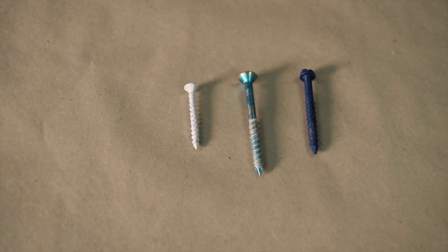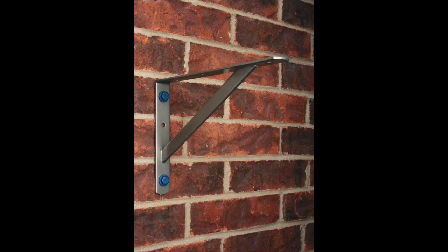Tack-on screws are manufactured with special threads that will thread into a pre-drilled hole in materials like concrete, concrete block, and brick. There's no plug that is needed. These screws embed into the material by tapping the threads through the material surrounding the hole, much like how we tapped metal in the metal tapping demonstration.